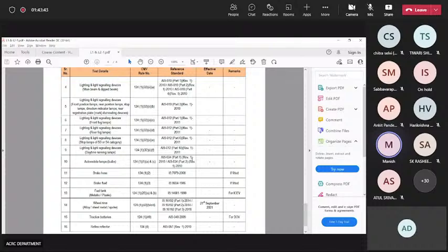These all happen before you submit your vehicle for final homologation at the vehicle level. So this part level has to be sorted out first. This will take you around 1 to 3 months just for part level certification. It will cost you around 20 to 50 lakh rupees for all these components to get certified, depending upon whether it's a two-wheeler component or a four-wheeler component. This is the part level certification.